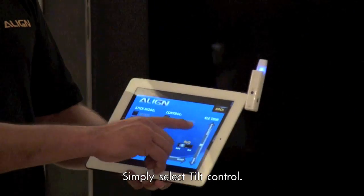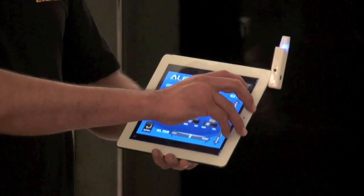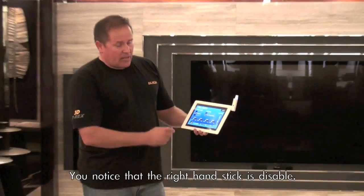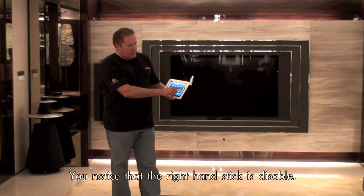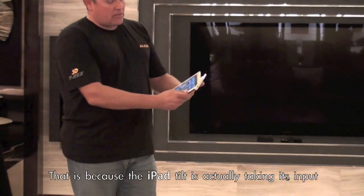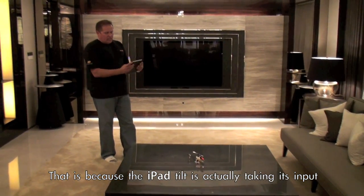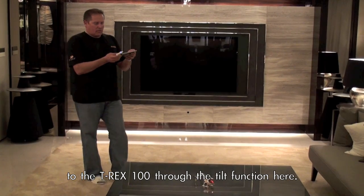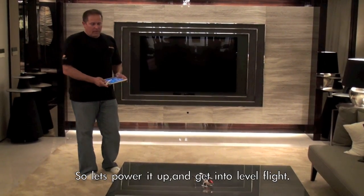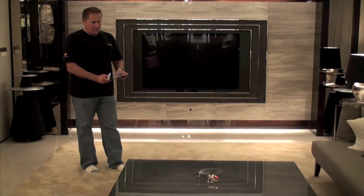Simply select tilt control in this panel here that you see here, and basically that is the setup panel. Just simply select that from the top button. You'll notice that the left hand stick is disabled. That is because the iPad tilt is actually giving the inputs to the TREX-100 through the tilt function here. So let's go ahead and power it up and get into a little flight here so you can check it out.